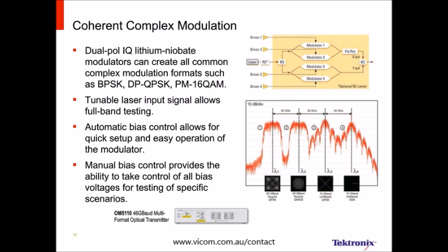But if you can spectrally shape this, that is, don't use a fast rise time square pulse, instead use a raised cosine type pulse, now you can get a square-shaped spectra, and so you can get a lot higher baud rate. This is 28 gigabaud, and it fits into a narrower slot than the 10 gigabaud because of the spectral shaping. So it's just another example of how being able to craft arbitrary waveforms is increasingly important.